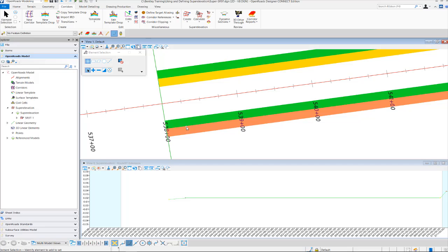westbound lane. So once again, just select one of your lanes here, select the 2% dynamic text, key in 1.6% to change the slope there. That takes care of the inside lane. Then go and select the outside lane, change this one to negative 1.6%, and that will adjust the slopes at station 538 plus 00. Now let's go insert our 2% cross slopes at station 540 plus 00.